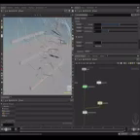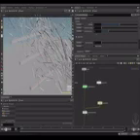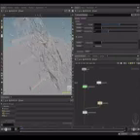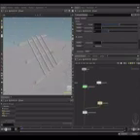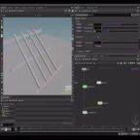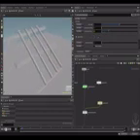Okay. As you can see, since we have a rest length attribute and the error reduction parameter is not 0, this is trying to set a distance of 1 between each piece. So let's set this to 0. Press play again.